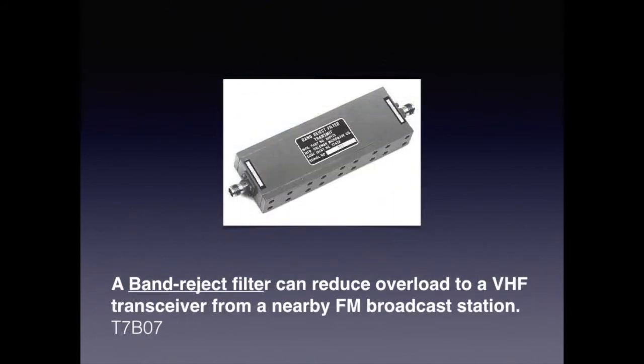A band reject or band stop filter is one that passes the frequencies that you desire, but it attenuates the undesired frequencies to a very low level. For the exam, know that a band reject filter can reduce overload to a VHF transceiver from a nearby FM broadcast station.